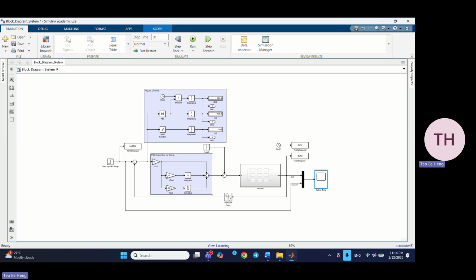control system. Instead of solving the equations manually, Simulink allows us to simulate the system response graphically so that we can get the response curve. The model also provides a platform to test the controller performance under different operating conditions. First, we need to put in the controller. Here, I use the PID controller to control the temperature.